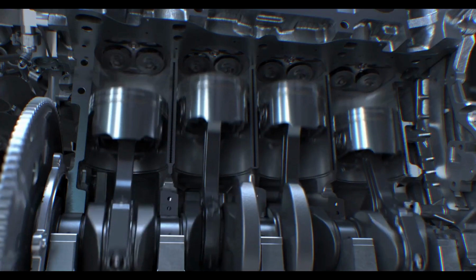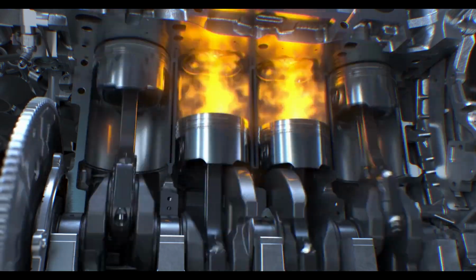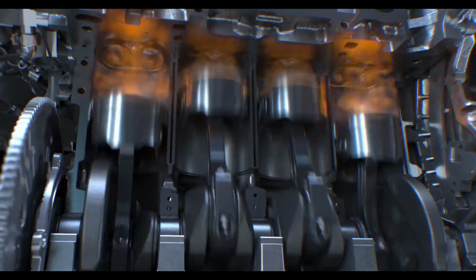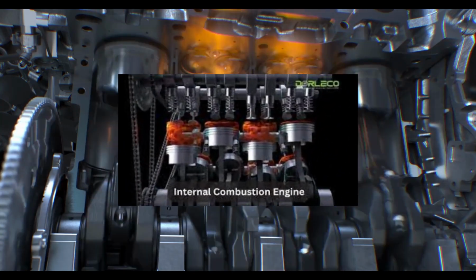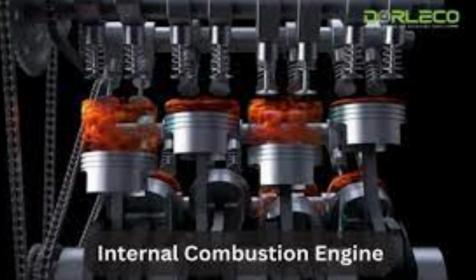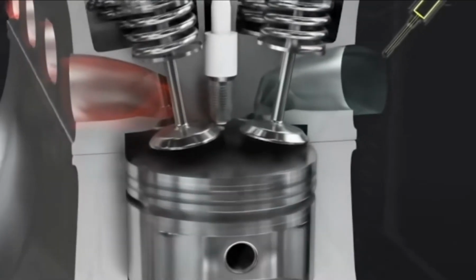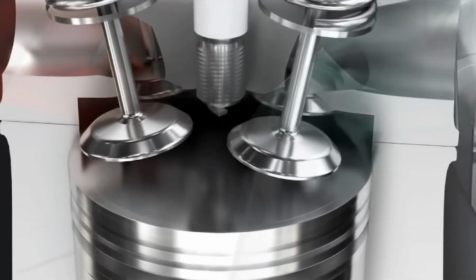Engine operation principle. Internal combustion engines work based on 2 main cycles: the 4-stroke cycle, commonly used in cars, and the 2-stroke cycle, found in some motorcycles and marine engines. The 4-stroke cycle consists of 4 phases. 2.1 Intake stroke. The piston moves downward, creating a vacuum inside the cylinder.